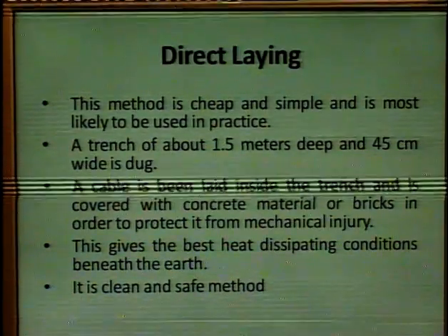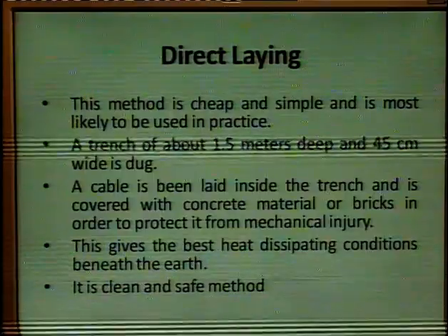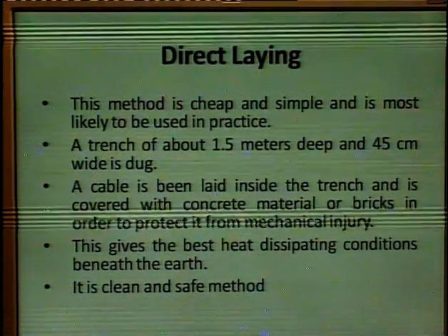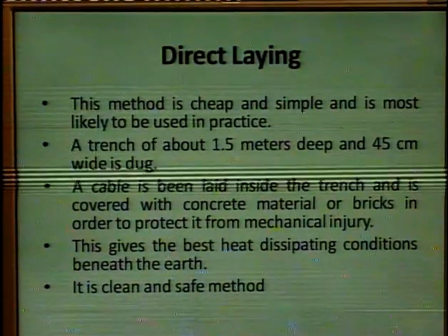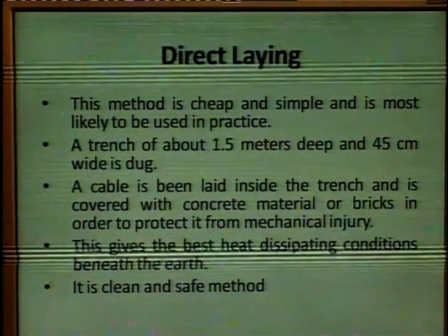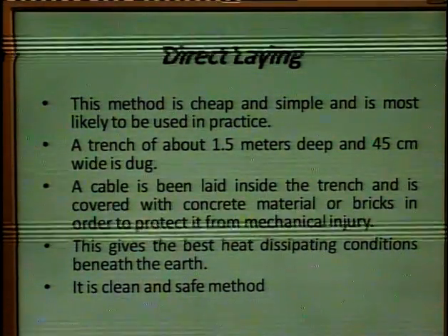A trench of about 1.5 meters deep and about 45 centimeters wide is dug. The depth and the width of the trenches depend upon the type of cable and the number of cables.